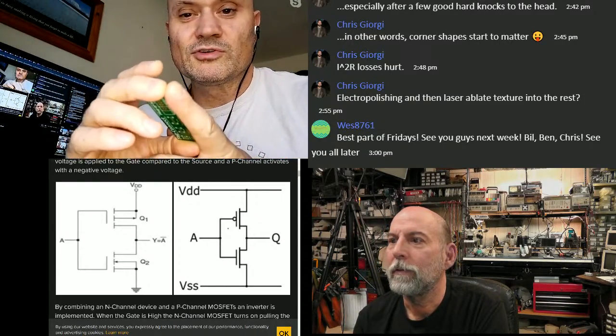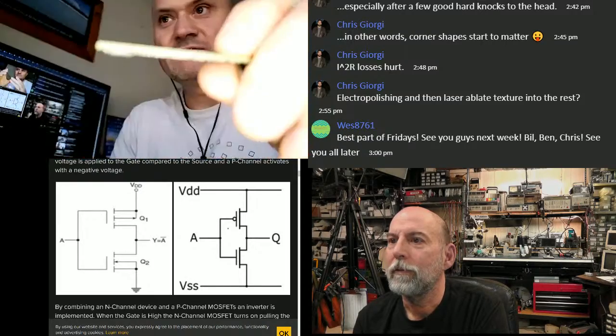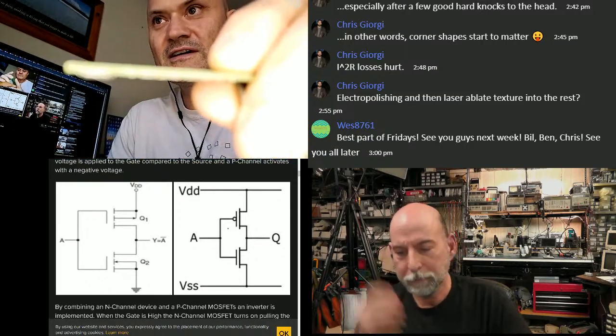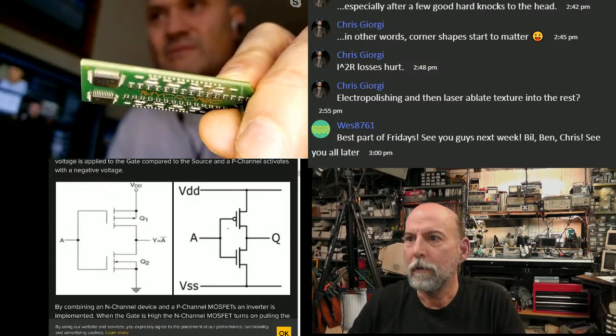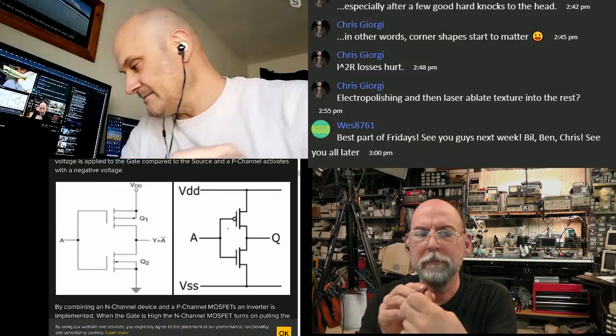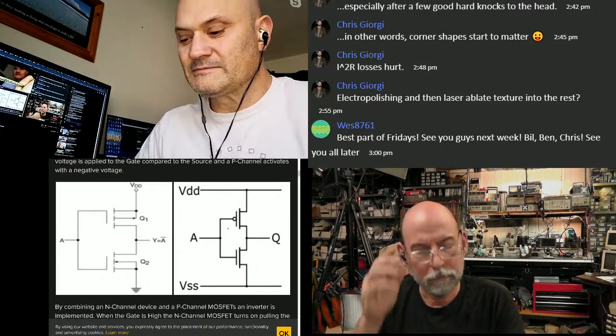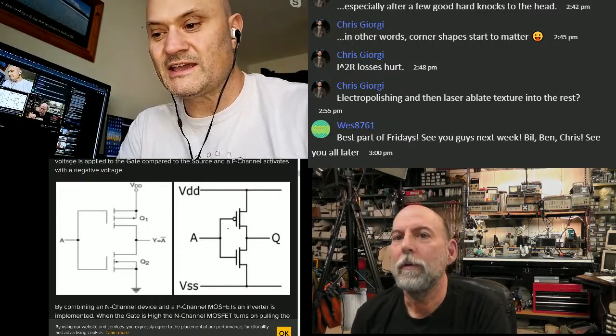It's kind of a brutal approach, but the more common one is V-scored. This one's been V-scored. Okay. So I can't get that to focus. So you see the edge of the board is not smooth, right. So there's some tolerance on the board edge. So the board edge itself should never be used as a datum.